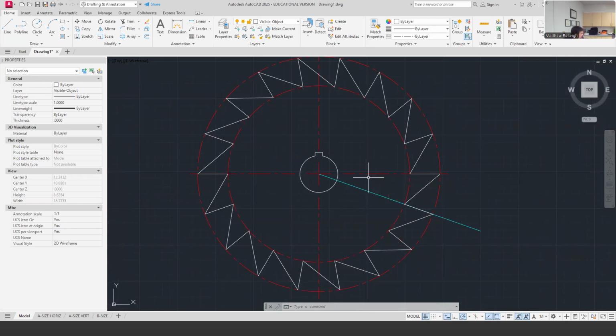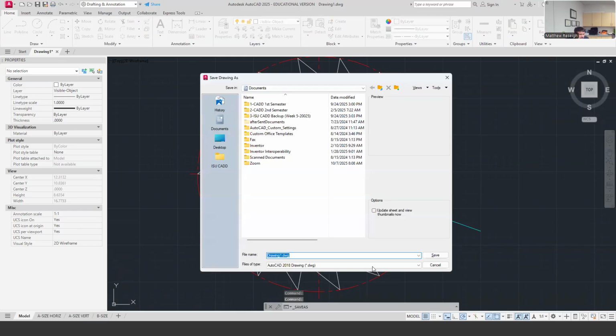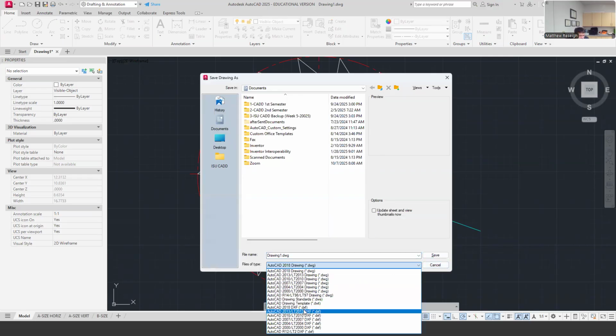I think I've told you before that a lot of machines use a machine file type, a DXF. Even 3D programs are able to export the flat pattern like this into a DXF file that will be interpreted by machines. So I could choose that type of file right here. Sorry, I was saying DWX, but it's DXF. I'm not going to do that now. I just want to show you that it is a common file type in your options to save this as a DXF, ready for machine interpretation.